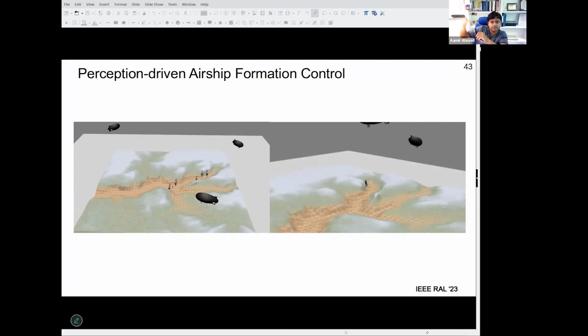So we take that as an airship-feasible constraint, but then still apply some angular separation, distance guarantees, and so on, that come from previous work that I talked about, and subject centering, and then solve these through an MPC-based controller. So basically, we respect the fact that airships always keep orbiting instead of flying just along the target. They keep orbiting, but now we move the whole orbit in a certain way that it keeps the target in the field of view. In doing so, we also find that the radius of the orbit around the target is coupled with the speed of the target. These kinds of findings we then embed back into the MPC constraint to ensure that the target is always in the field of view.